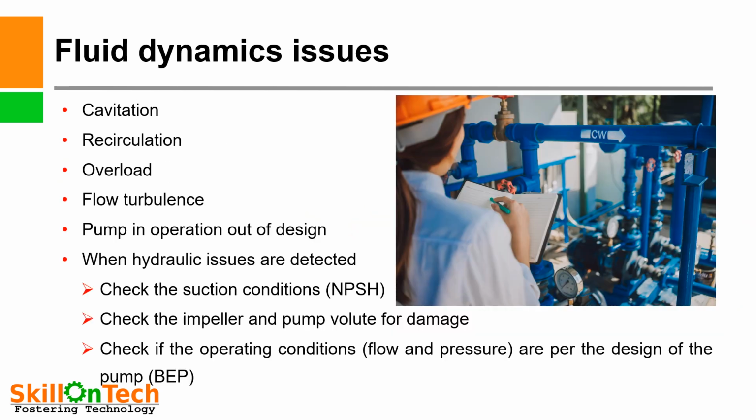Other than mechanical reasons, there may be some important fluid dynamic issues which may cause vibrations in the pump. So what are these fluid dynamic issues? Cavitation, recirculation, overload, flow turbulence, pump in operation out of design.